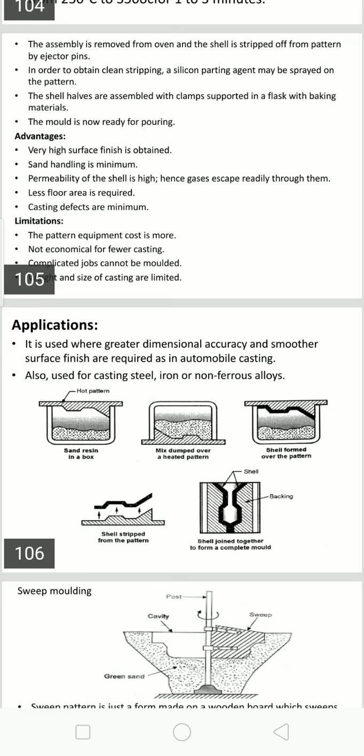A greater quantity of binder is required, which gives a good surface finish on the casting. Coarser grains require less binder but will not yield a smooth surface on the casting. The first step is purely related to molding mixture preparation. Second is pattern heating.